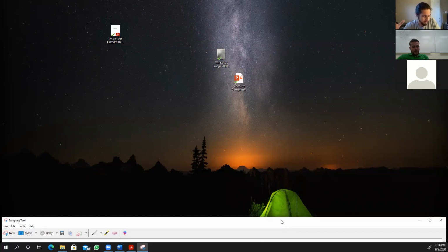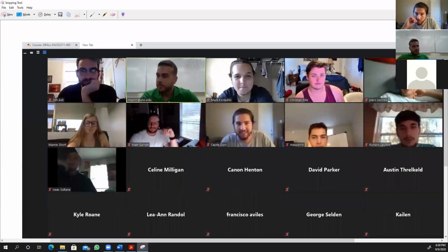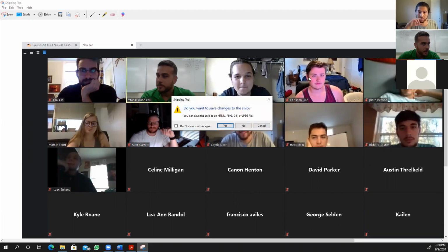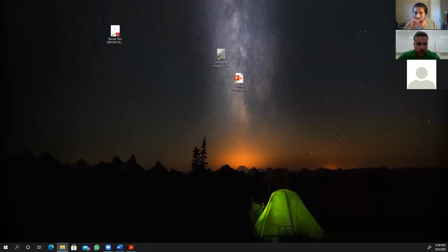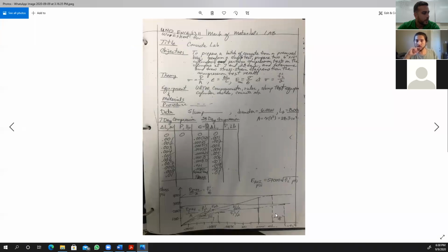For tensile, it's when it is less than yield strength, but for concrete, it is when it is less than half of the F prime C. Okay, half of the F prime C. One second. It was on the handout, and I'm positive it's half of F prime C. Right here.